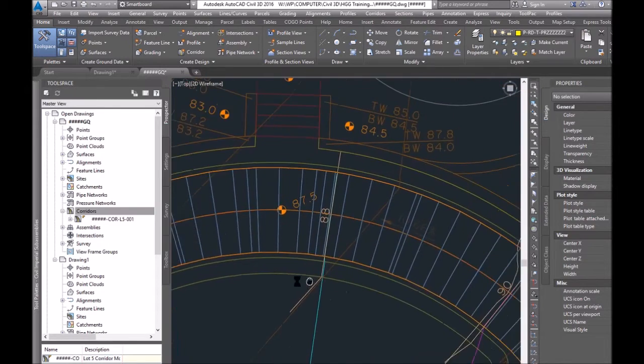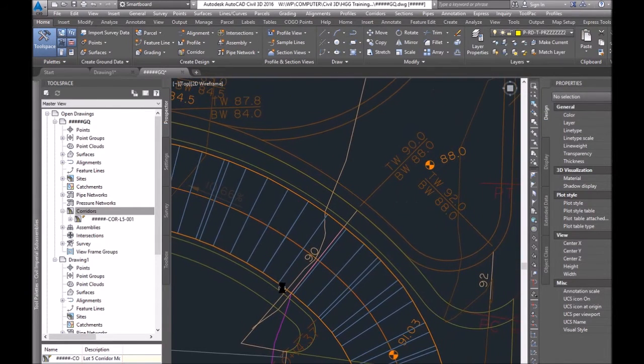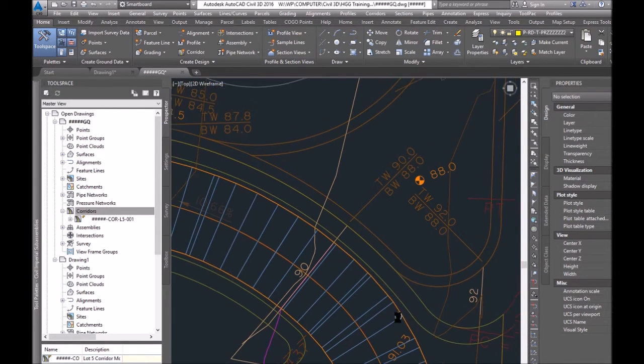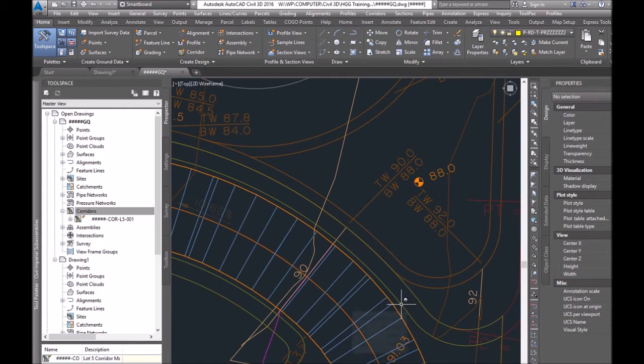So the next thing I'm going to want to do with all of these assemblies is specify targets. Basically, the subassemblies can be defined as an equation targeting a polyline at a certain length, or you can even target feature lines or other road profiles to get certain target elevations. So in our case, this is the driveway, and then this is, I think, a gravel strip or concrete, just patterned concrete. So I'm just going to model it all the way too.